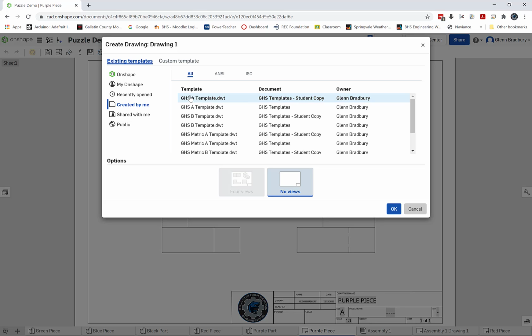And you can see by saying that that's the front view now, my top view has added a hidden line for this surface here. And then my right side view still has a hidden line because of the surface that's back there. So that's not really a great view. I can right click on it again and change it, and maybe we'll try the bottom and see what that looks like. Again, the program automatically updates this for you.